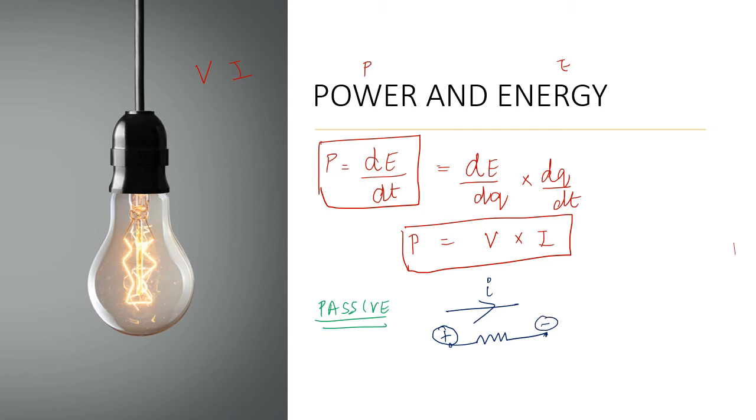That is, voltage is dropping in this direction, from positive to negative. If the direction of current and the direction of this voltage drop are the same, then we assume a positive sign for all the power calculations. If the voltage drop and the direction of current are opposite, or different, then we have to take the negative sign.